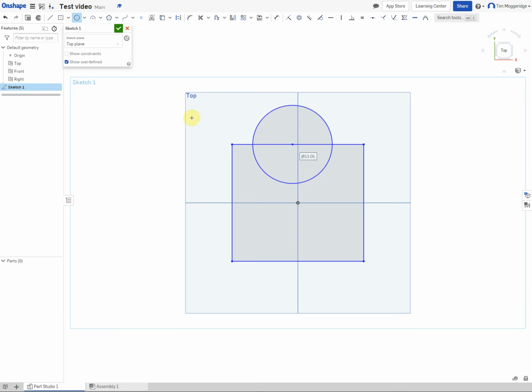moving down. So to turn this into a sketch that is valid, that follows those rules, I need to trim away some of the parts. So I'm going to use the cutting tool, and I'm going to cut away the inside circle or arc and the two lines here as well. So now we can ignore the dot. That's just showing us where the center of the circle is. We now have points that only have two lines coming away from them.